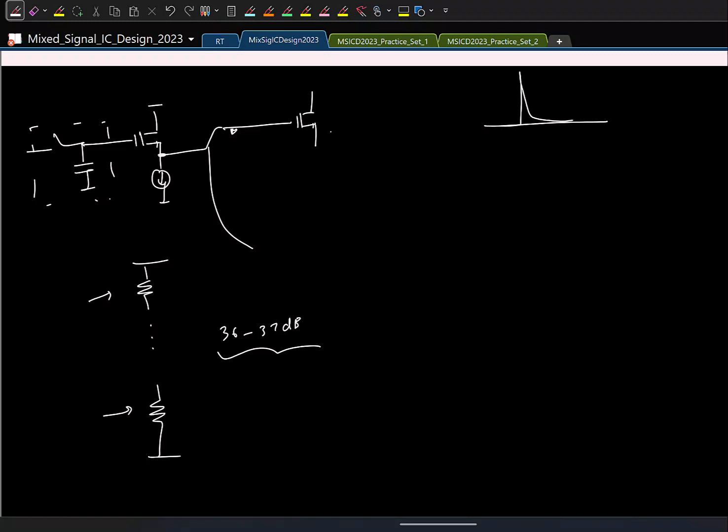So now we have seen flash. Let's actually look at some of the non-idealities we can have here. Right? And remember, in the flash, the only thing that is there is the comparator. So let's see what are the non-idealities we can have in the comparator. So when we looked at the op-amp non-idealities in the switch capacitor circuits, what are the non-idealities we considered? Yeah, first we looked at offset, and by extension the flicker noise, and we looked at the finite DC gain, and we also looked at thermal noise, how to analyze thermal noise.